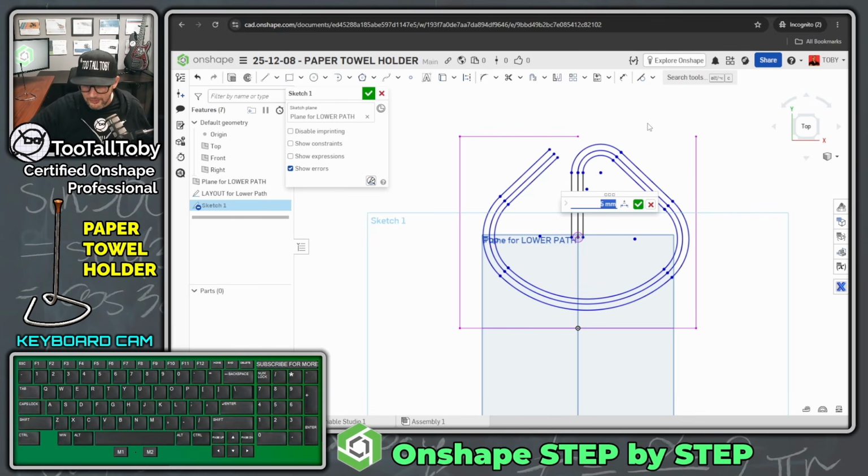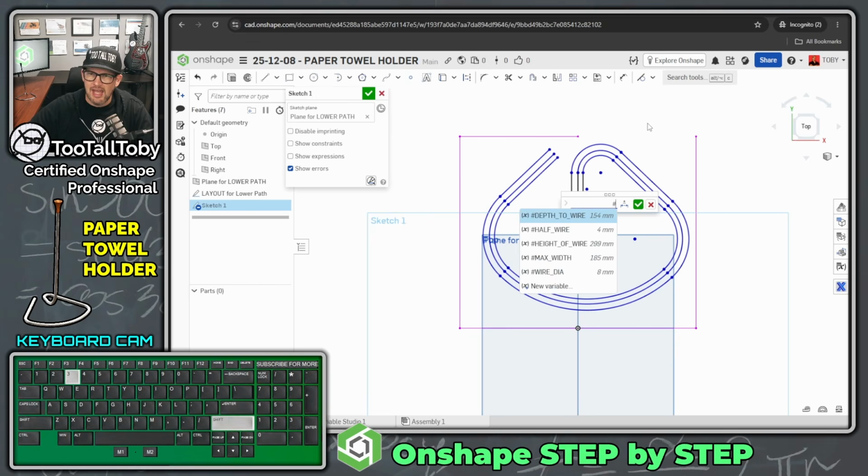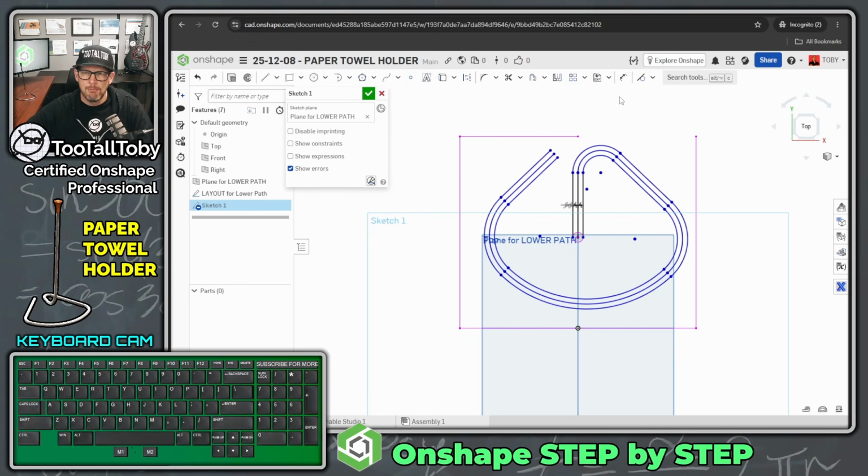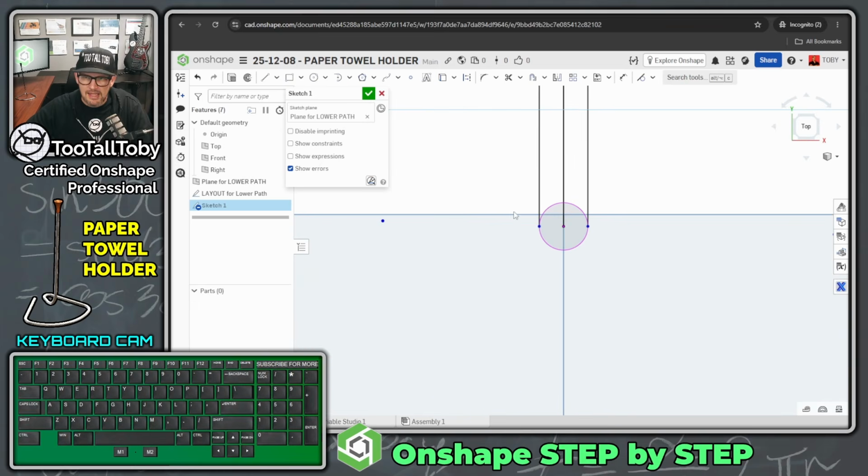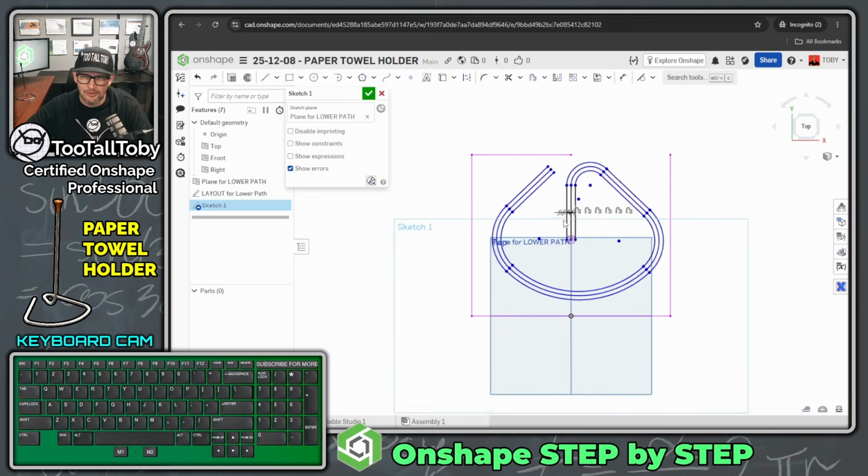And now what's that offset going to be? It's going to be hashtag, and then we go down here to 1/2 wire, enter, enter, and boom, we're done. If you did it correctly, then the diameter should match up here. The offset should match up here to your wire diameter from the layout sketch. So it should match up here on either side.